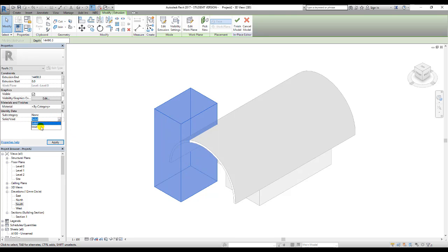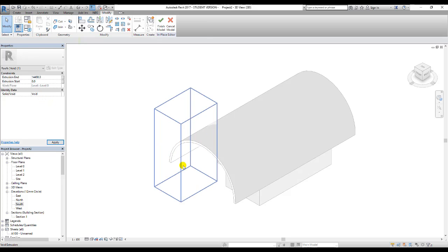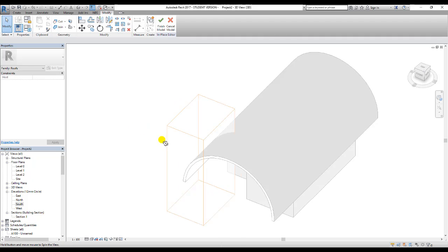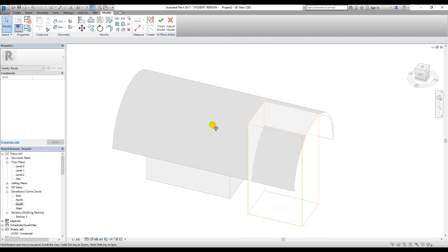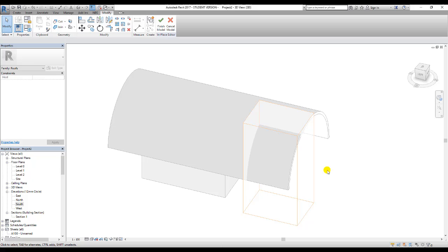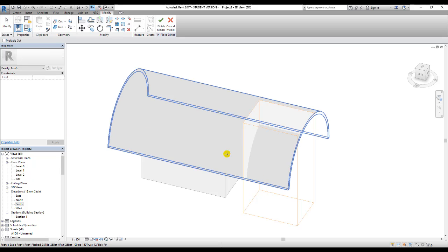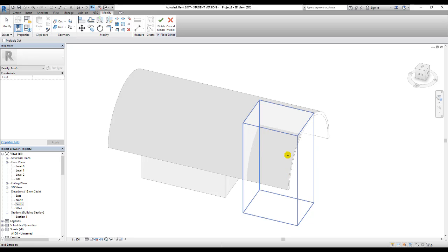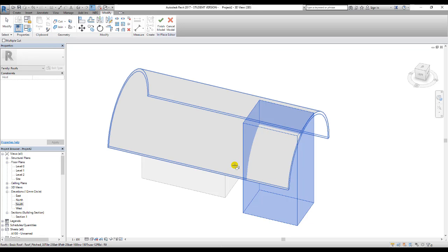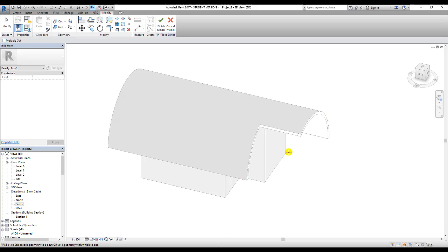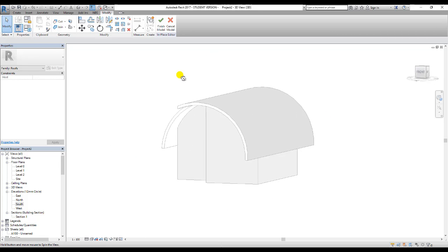It's not massively problematic. Make the void, then this changes to the orange line, then we just subtract one from the other. So we use the cut tool, and I either select the void form then the roof, or the roof then the void form. It matters not, but choose one then the other, and that forms that cut through that. And then I can say finish model.